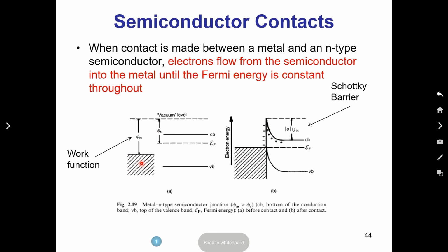and if you measure the electrical conductivity of your sample, obviously you're going to get the electrical conduction that is associated with the overcoming of the Schottky barrier. So the sample's conductor resistance is what you want to measure. But instead you measure the contact potential related resistance. So clearly that's not your sample.